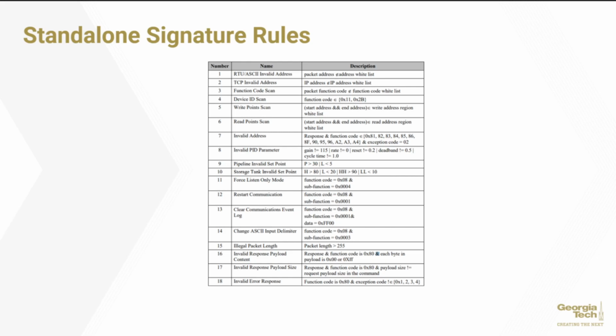They have provided signature rules, which are described in this table, and these rules can be adjusted to any cyber-physical system, as long as you have an expert on the specific system you are working with, in order to provide the parameters for tuning the signatures for that environment. A system-specific whitelist can be developed, which includes all legal function codes a Modbus server supports. The function code whitelist can include all public Modbus function codes as well as any user-defined function codes.